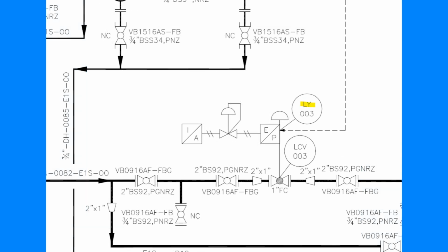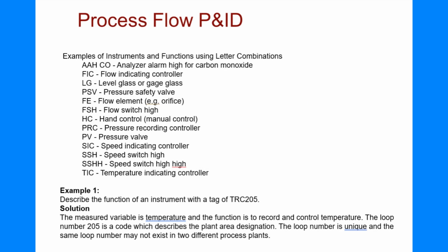The letter Y, used as a succeeding letter, means relay, compute, or convert. There are many different types of relays, computing and converting devices, so a written description is often required on the diagram. This slide shows examples of instruments and functions using letter combinations.